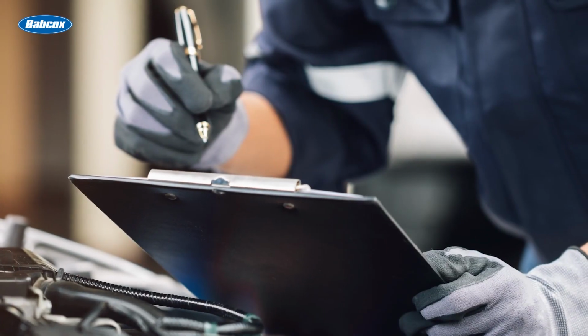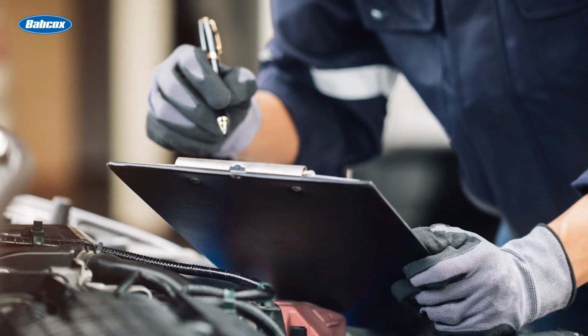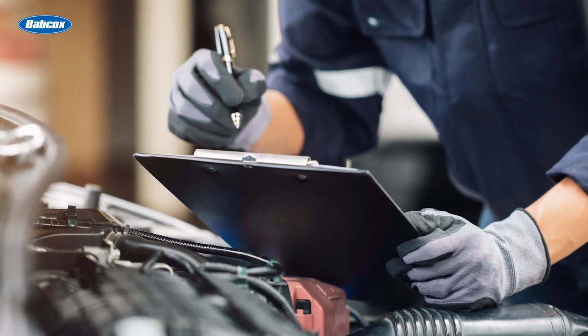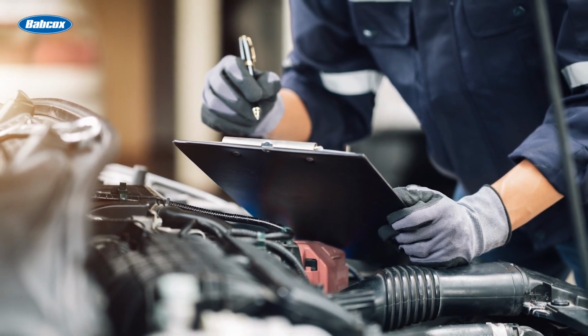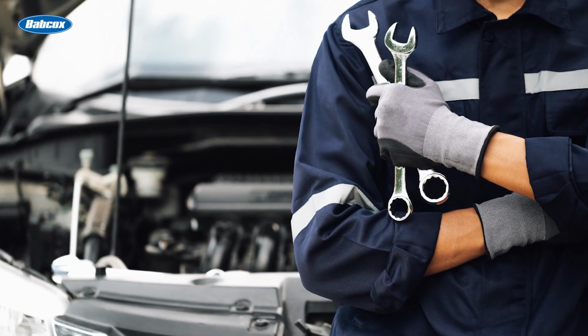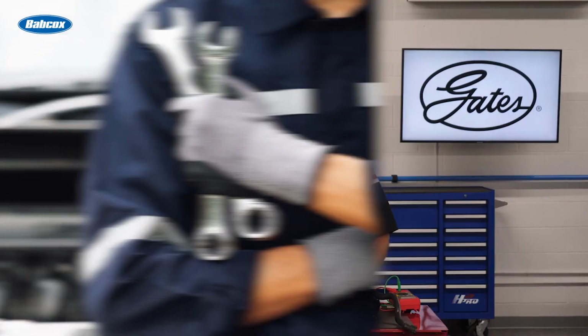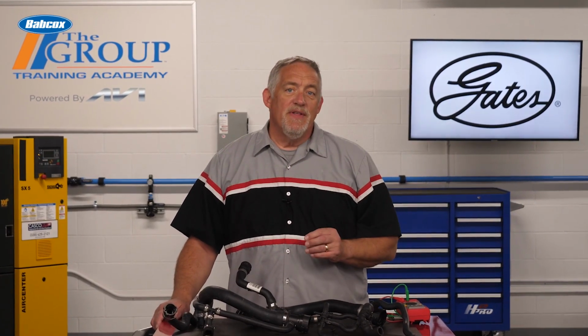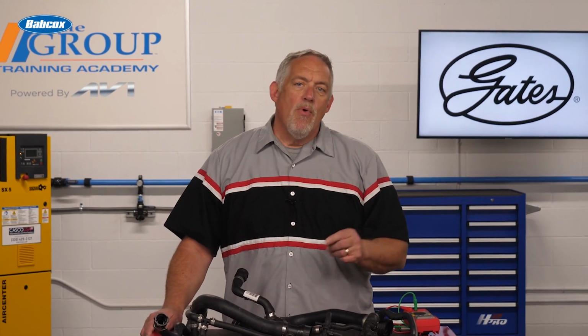Inspections are critical because it's not uncommon for hoses to look new at 60,000 or even 80,000 miles. Regardless, most maintenance schedules require periodic inspection rather than a replacement interval. Check them carefully for degradation and damage every time you're under the hood. The cooling system is called that for a reason. When one component within the system fails, other components are soon to follow. It's now more important than ever to maintain a vehicle's coolant system.